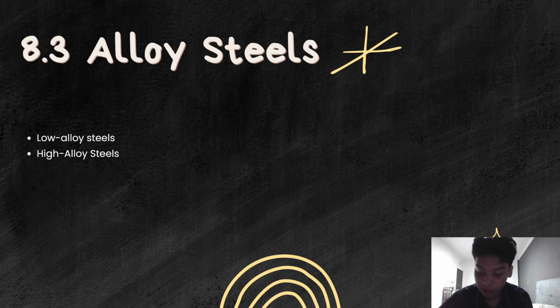Low alloy steels constitute a category of various materials that exhibit mechanical properties superior to plain carbon steel, resulting from additions of alloying elements such as nickel, chromium, and molybdenum. High alloy steels. Steels with alloying greater than 9 weight percent are typically classified as high alloy steels. Stainless steels are the major type of high alloy steel, but two other types are ultra high strength nickel cobalt steels and maraging steels.